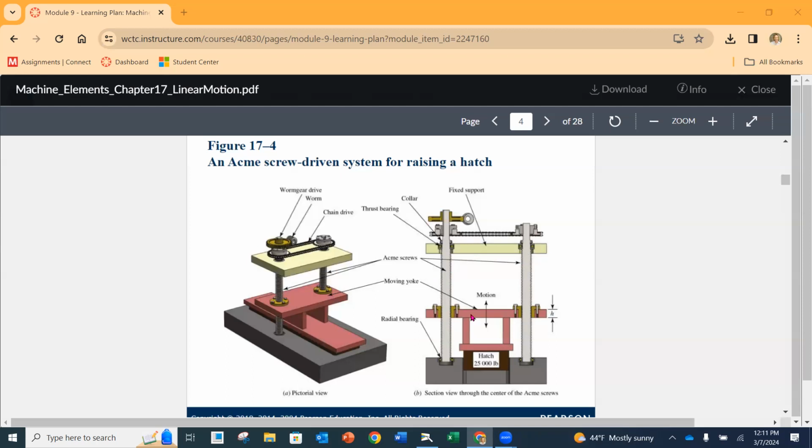Other considerations that we need to think about when we're looking at these lead screws, as they talked about in that section: what the pitch is, what the rotational speed of the lead screw itself needs to be, so that we can accomplish that travel of 15 inches in 12 seconds, right? One way and then the other. Good. Yep, the size, the pitch.